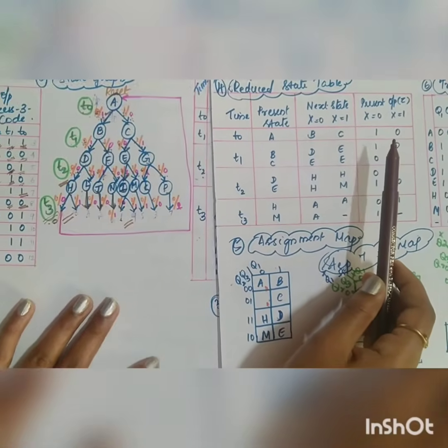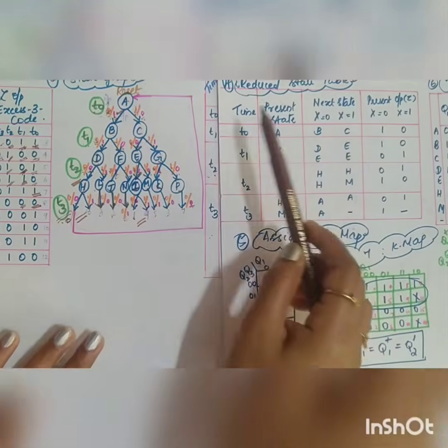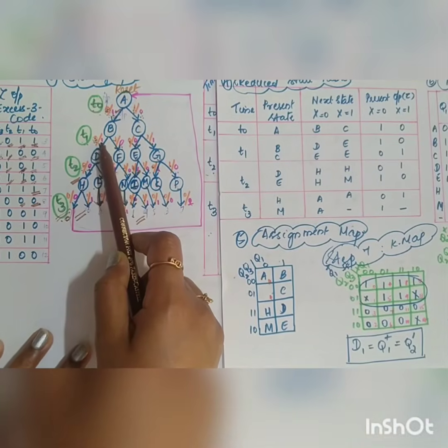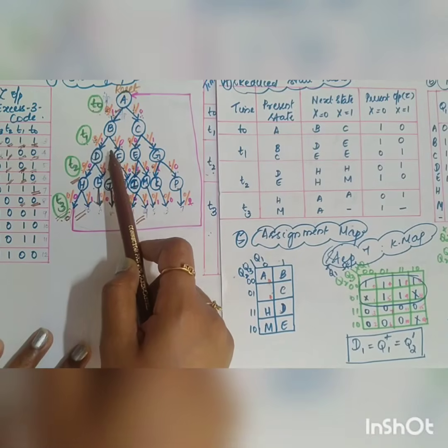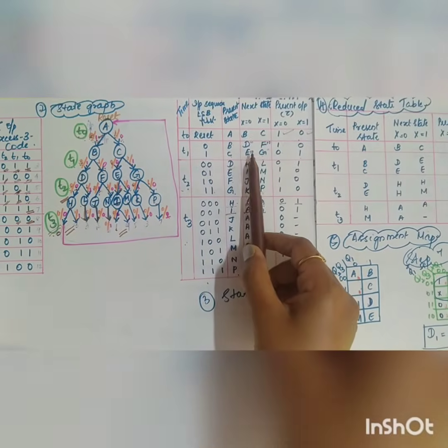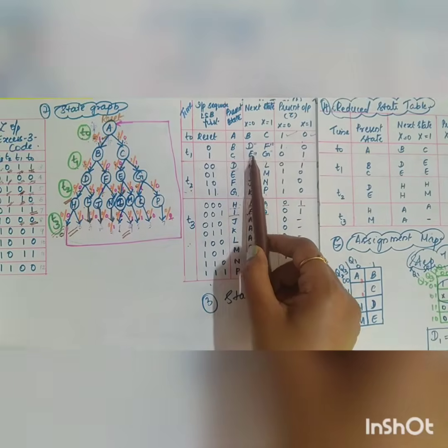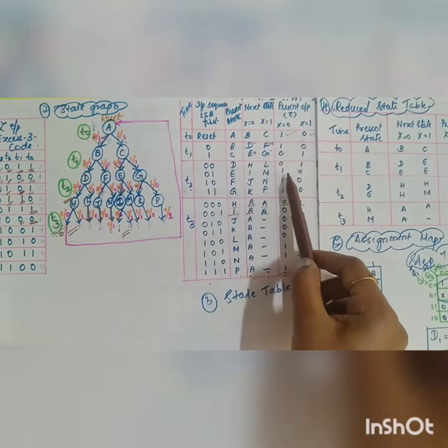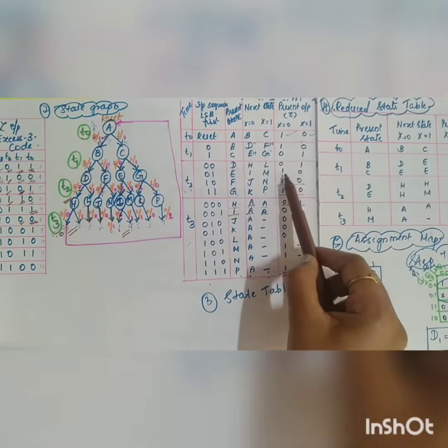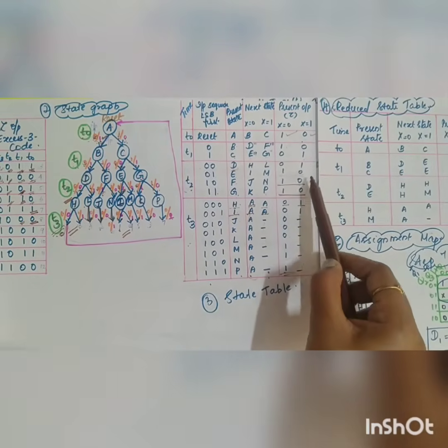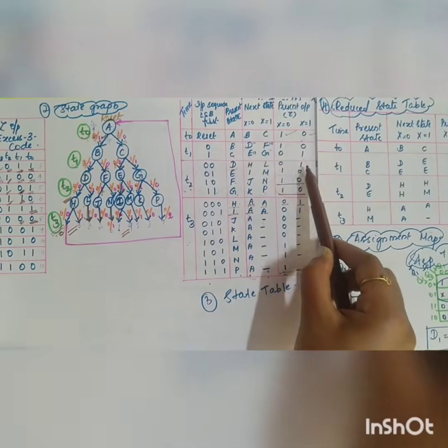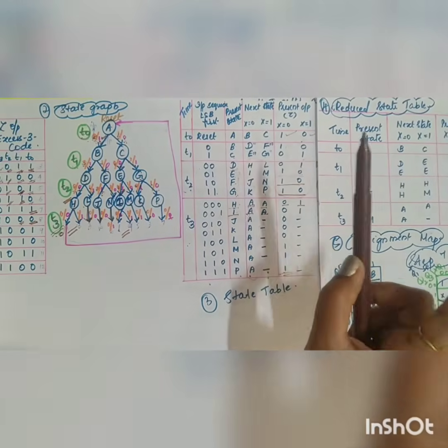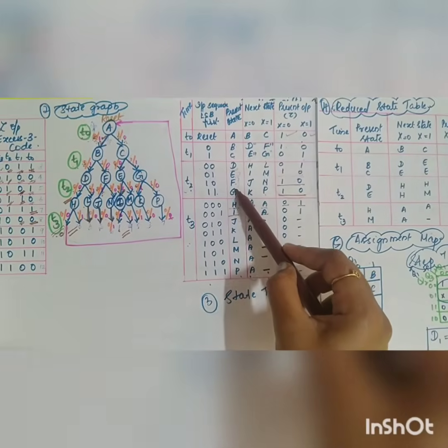But when you see your diagram here, when you see your state graph BC, here you have input and output. If it is similar, you are going to reduce it. So in the case of next state, that is next state D, E, F, G, you can see the outputs are similar, right? 1, 0, 1, 0, 1, 0. So instead of taking this 1, 0 with 3 separate states, I can take E, F, G as one single state. That's what is done here.